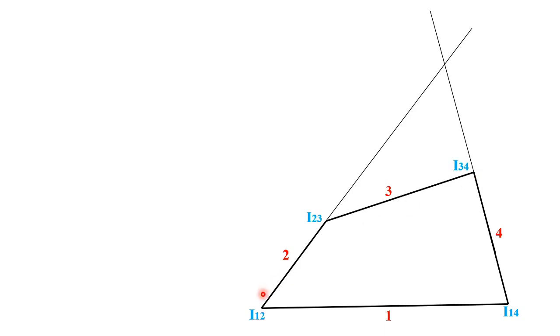Again I will explain. We have 3 bodies 1, 2 and 3. Therefore, the associated centers are I12, I23 and I13. So what we can say is I13 will be on the line joining I12 and I23. So this is this line. Similarly, we have another set of bodies 1, 3 and 4. So I13, I14 and I34 will be on the same straight line. So you join I14 and I34, which we already located. So I13 will be on the same line only. Both lines meet at this point. That means there is no doubt that this is your I13. This is how you locate I13.